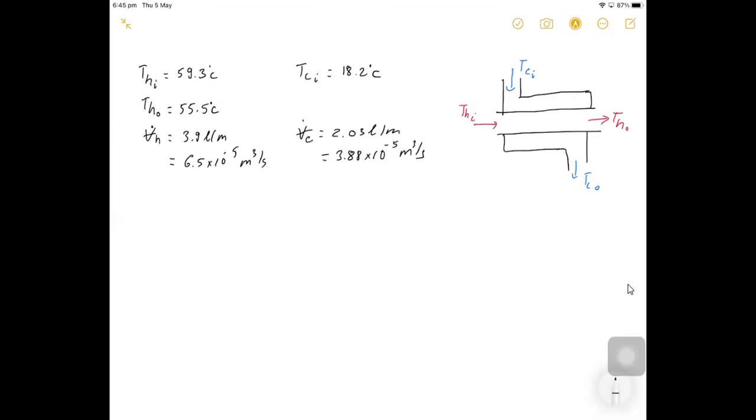Before designing a heat exchanger, we have to make some assumptions, like the materials of the inner and outer tube, and the inside and outside diameters of the inner and outer tube. For example, for the inner tube, this data is exactly the same as the heat exchanger you used in the heat exchanger lab.